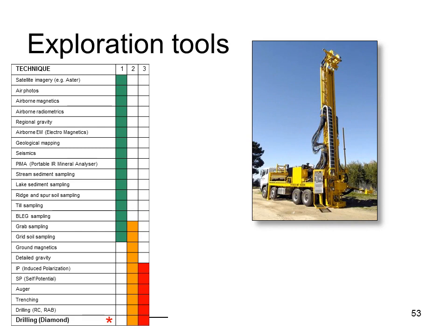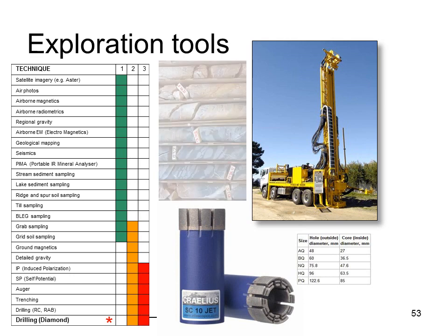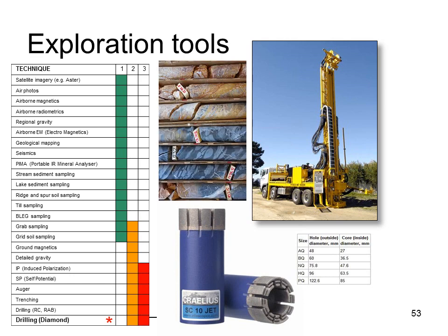Lastly, diamond drilling or core drilling. This is the ideal method for most exploration, but is generally about 3 times the cost of RC per meter. The phrase diamond drilling refers to the drill bit, which is studded with industrial diamonds in a metal matrix. It produces a core of solid rock, which provides much more geological information than RC chips. A diamond drill can reach between 300 and 4,000 meters, depending on the rig type.